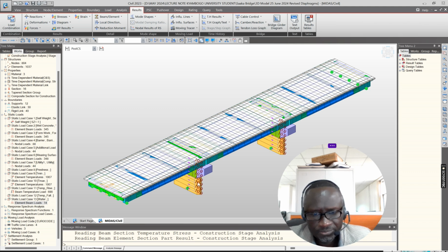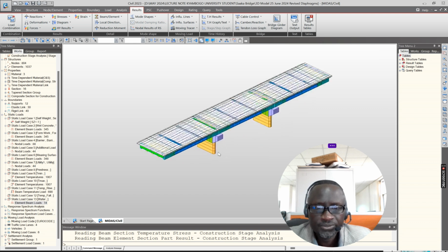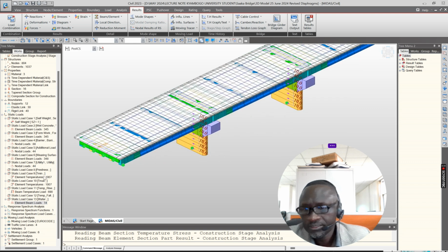As water is passing through this bridge, it tends to push and drag. So the entire formula used for aerodynamics is basically applicable here, except you've now replaced the density of air with density of water, and the speed of wind with that of water. So that is what we could do in the loading.